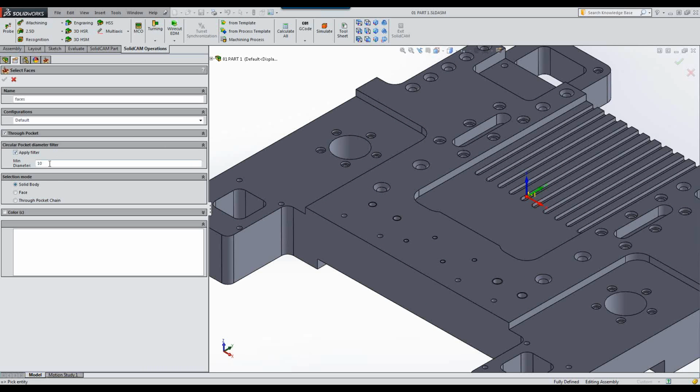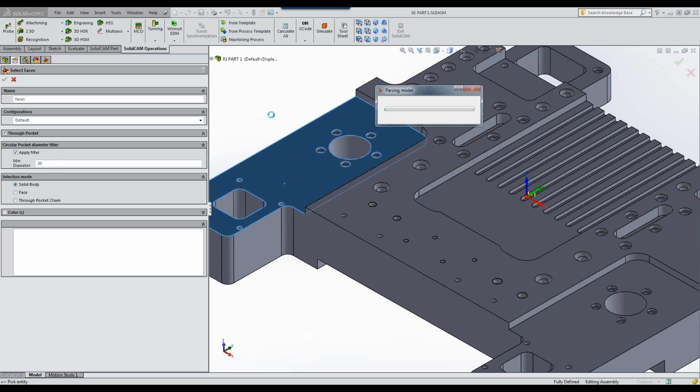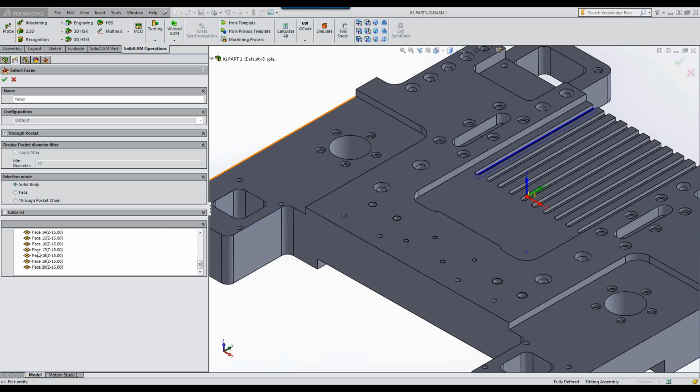So I'm going to say, okay, anything, I'm going to put my marker over here, any diameter that is less than, now click on this diameter over here, less than whatever that diameter is over there, do not accept that as a geometry. You can see it automatically updated this field as well. Now just click on the part itself, and it builds all of the geometries as shown over here.